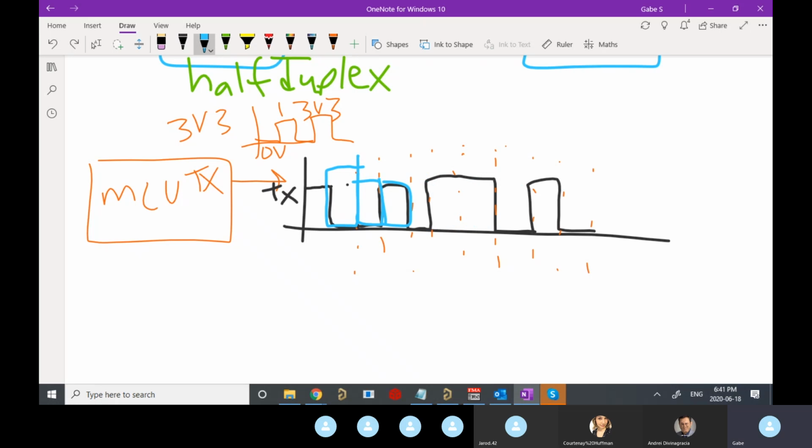So the very first thing we send is a start bit. All this does is it tells whoever we're talking to that we've started. We've brought the line down to ground, down to 0 volts, for one bit of data, to say, hey, we're going to start. And remember, this has to last as long as our baud rate defined, right?